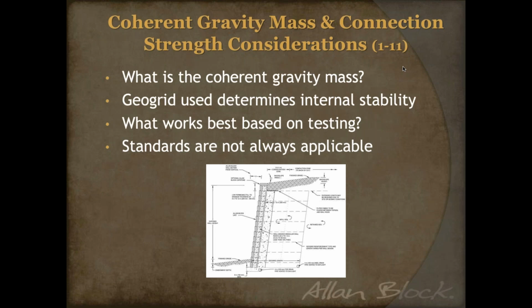So it's important to look at your unique site, your unique project, and say, how does this affect my wall? Am I going to need to extend my geogrids? Do I need to have more layers in certain areas? It's just good to be aware that the standards aren't always applicable. And just like everything else, it's a unique application, so it might require a unique solution.